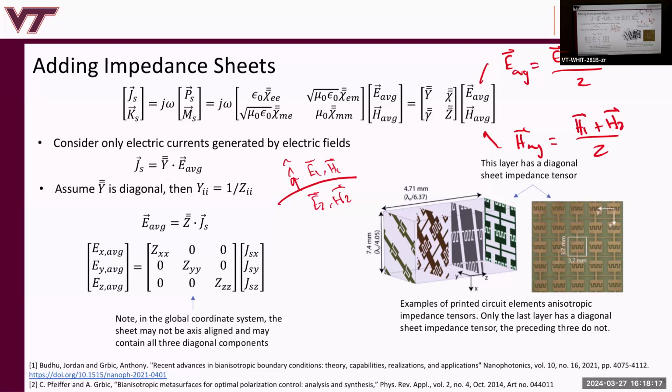So this is a boundary condition that you use to design metasurfaces. It's very related to the impedance boundary condition. In fact, it can collapse to that. And it kind of bears resemblance to the constitutive relation J equal to sigma E, if you consider only electric impedance sheets. But that's a loose analogy because the constitutive relation J equal to sigma E is for a medium, right? Sigma is a parameter that describes a medium. These are interfaces, all right? Okay, good.